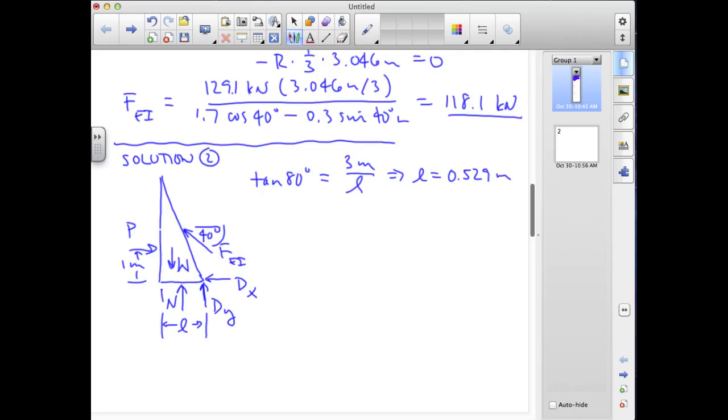So we'll calculate some values here. For the normal force, we have the pressure at A, the hydrostatic pressure from the concrete, times the span S times L. That's equal to the line load at A times L. And if we plug in 8.476 times 10 to the 4th newton per meter for the line load at A, times this length L of 0.529 meters, we end up with 4.484 times 10 to the 4th newtons.